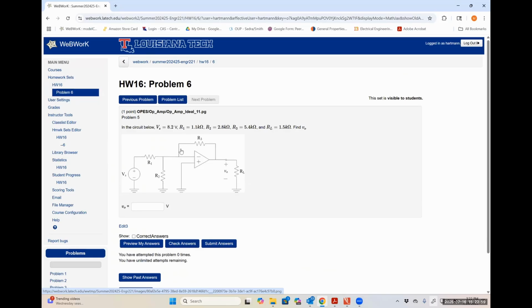And there's going to be some current flowing up and to the right through R3. So you would have 3 terms in your KCL expression. Now let's revisit this R2 thing. What is the voltage present at the non-inverting input node, which would be this node right here? It'd be 0 volts. Okay, so that means what's the voltage at this node? 0 volts. So what's the total voltage drop across R2? 0 volts. So there won't be any current flowing down through this one. So in your KCL equation, if you included it, it would just be 0 minus 0 over R2, which is obviously 0. Okay. That makes a lot more sense.